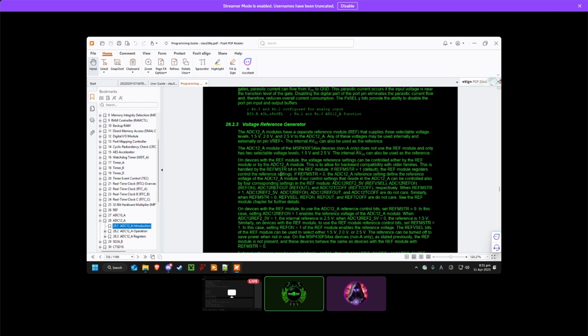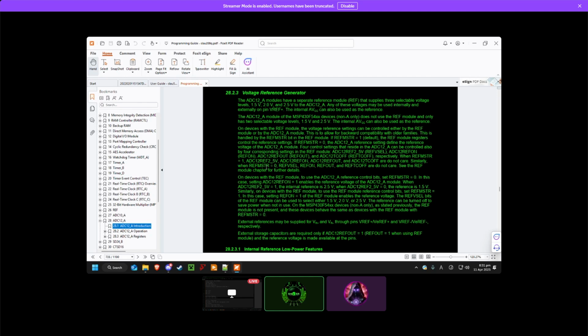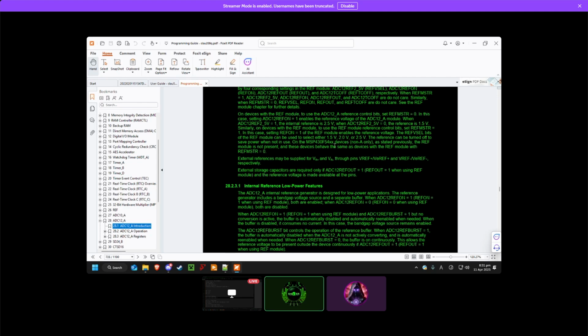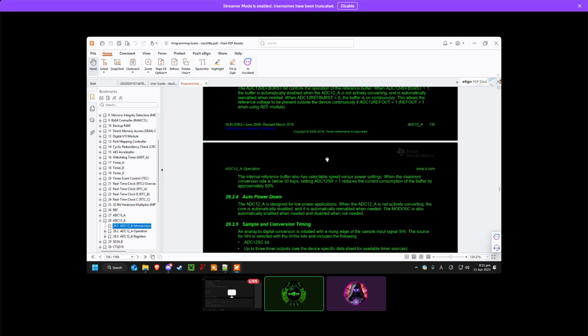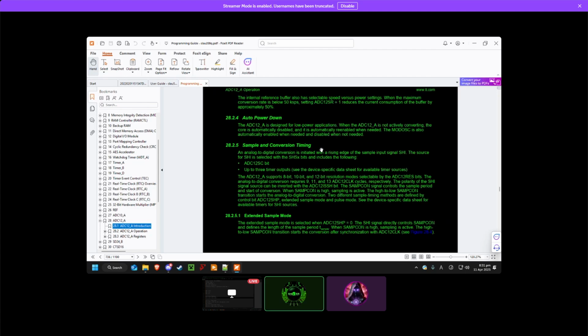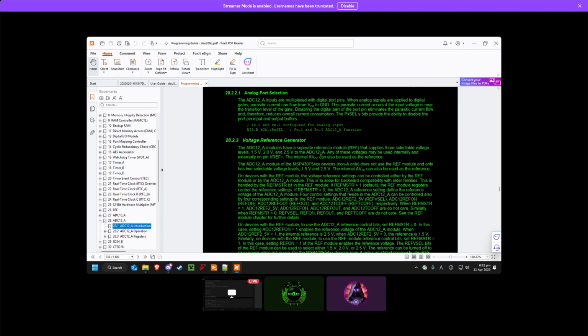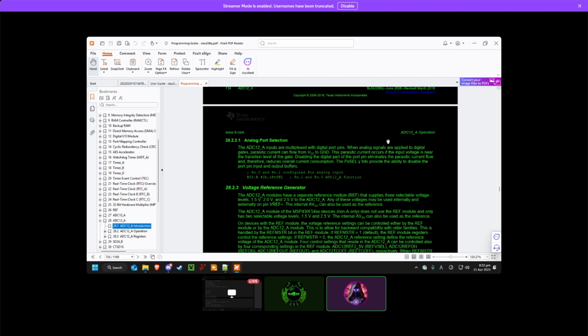So we're using internal 2.5 volts, but eventually we will need an external voltage reference so we can go over 2.5. And there is a limit on this, and I believe the limit is 5 volts. So we will have to limit that because the charge amp is capable of going up to 10 volts. Yeah, and just to note, if it does go above its 5 volt capacity, it will basically fry. So be very careful about that. Correct.